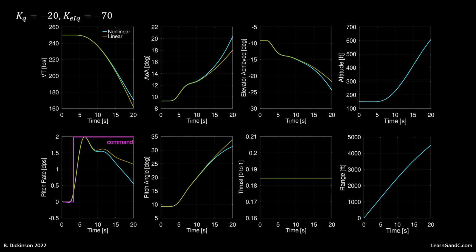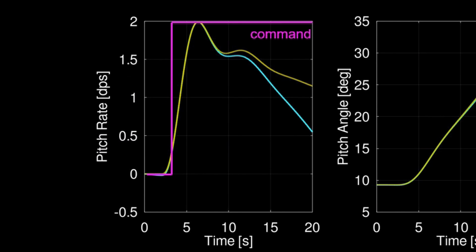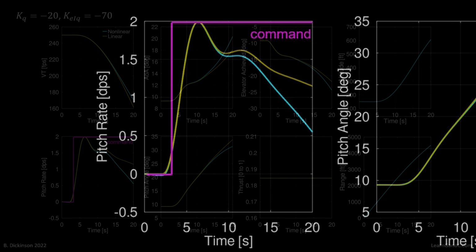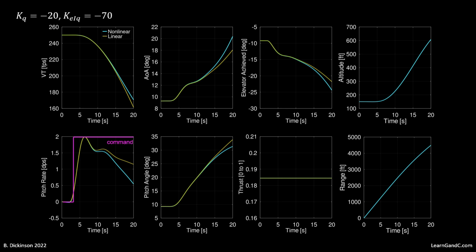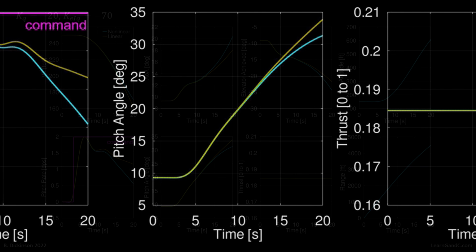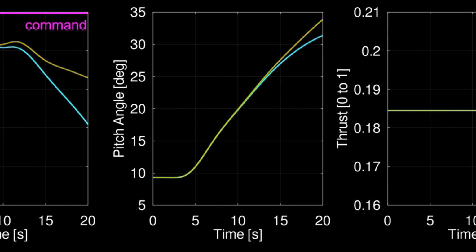Running the simulation and comparing the linear to the nonlinear equations of motion, first, we find excellent agreement between the two sims. And second, we see the short period and phugoid in the pitch rate response as expected. The step pitch command would be like pulling back on the control column, which, as we can see, produces a reasonably well-behaved pitch angle response in the airframe.